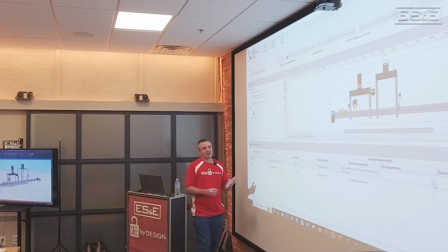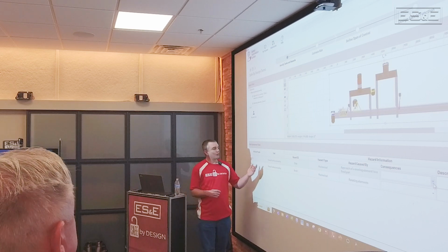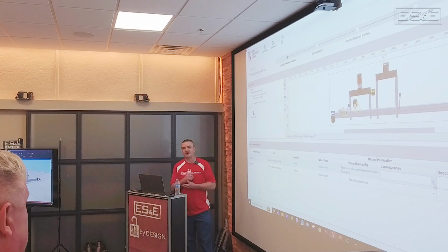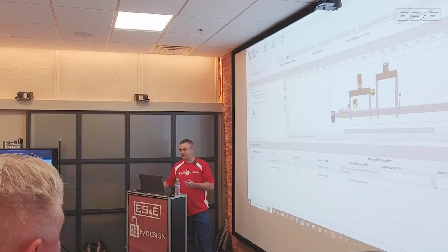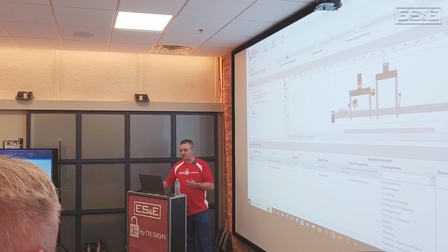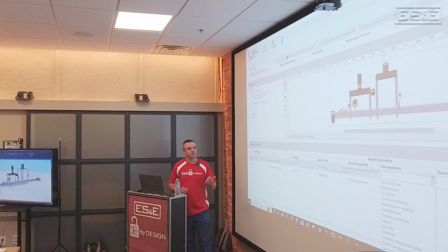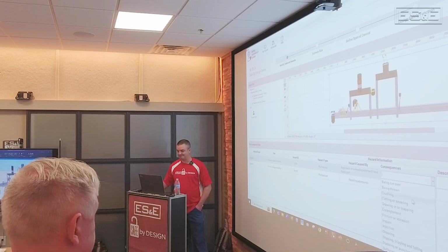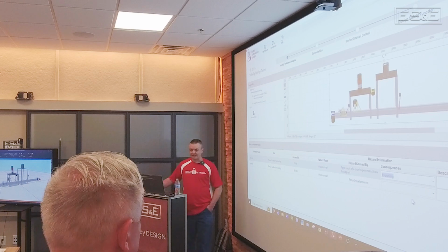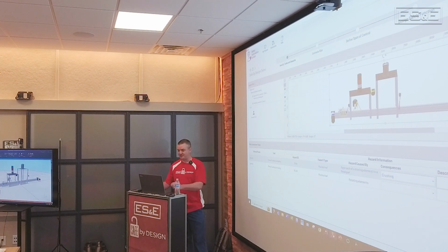Now going back to our hazards, we have to rank what the consequences of each hazard are. And this, again, is part of our risk assessment process. So when I start looking at that approach of that moving element or that slide, based on this list of things that commonly happen there, is there anything you could see that maybe... Definitely crushing. Could definitely see crushing being a consequence there. Probably the most. I think that would be a good choice there.